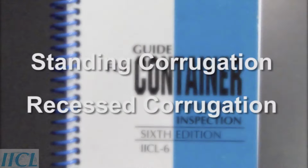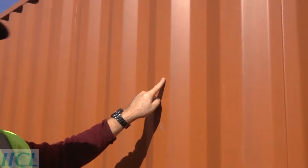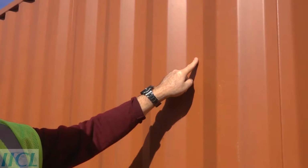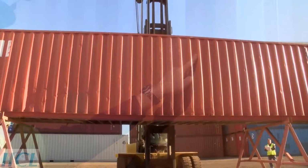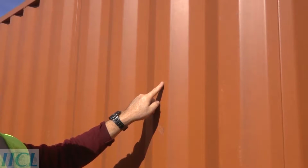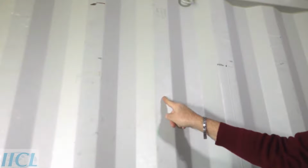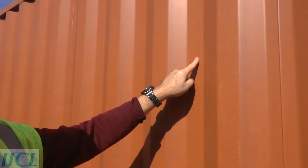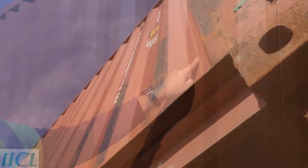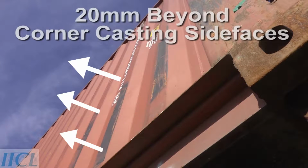The terms standing corrugation and recessed corrugation are used in the IICL 6 guide. A standing corrugation is the flat corrugation face that is towards the viewer, while the recessed corrugation is the flat corrugation face that is away from the viewer. The definitions apply from the viewer's position such that a standing corrugation when viewed from the outside is a recessed corrugation when viewed from the inside, and a standing corrugation on the inside is a recessed corrugation when viewed from the outside.